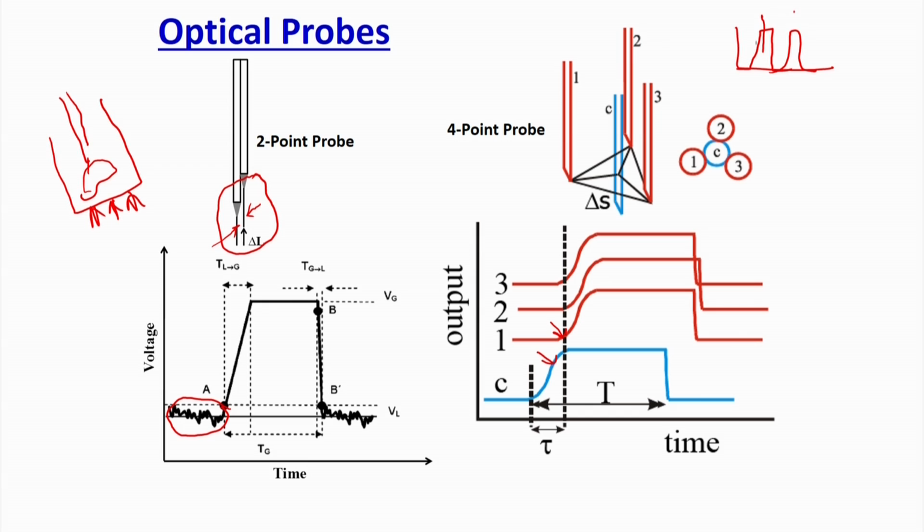So, what I can get is the distance between these 2 peaks, and that distance between the 2 peaks is actually specifying the delta t value, because the x axis is time, and this is volt. So, the difference between the two peaks will give me the delta t.